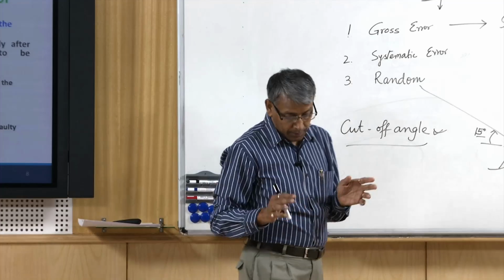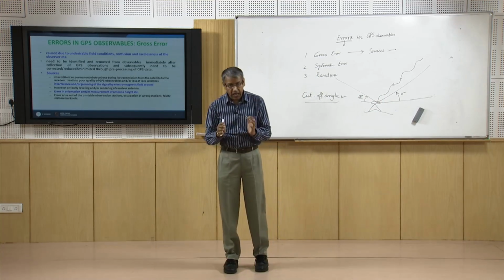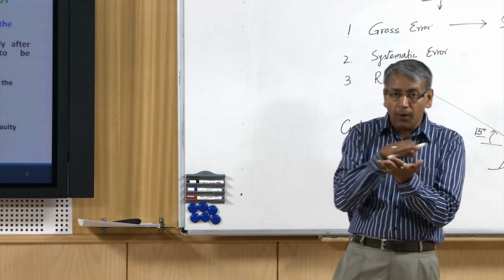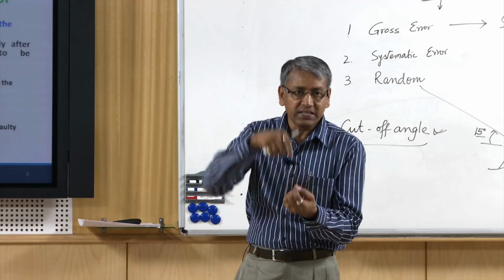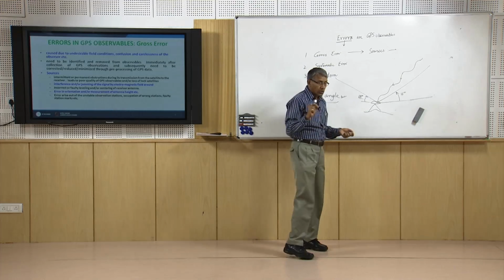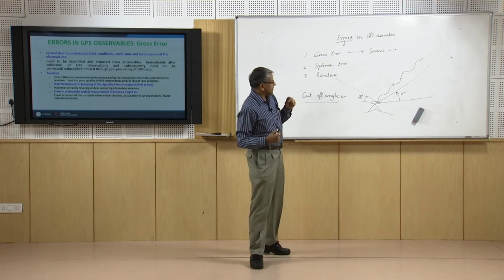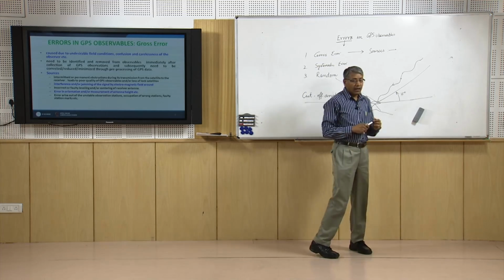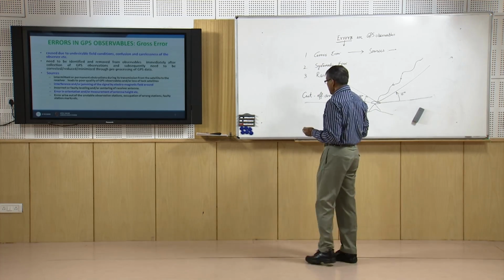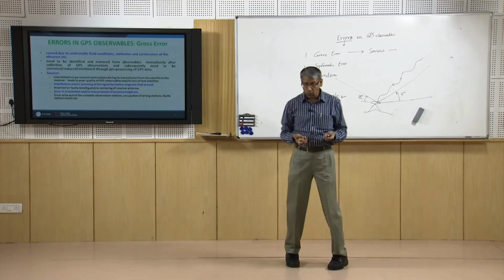Before setting up the instrument we should take care that the station is on stable ground and has been properly leveled as well as centered, and the parameters to be noted down, like the height of the instrument and many other parameters we will need, have to be noted down properly for subsequent use.